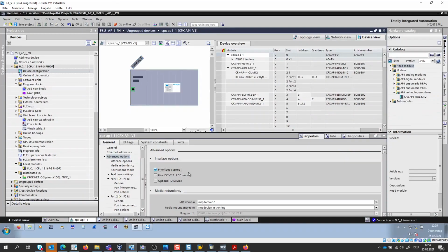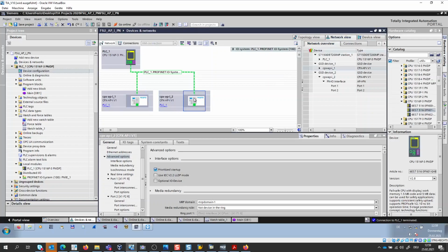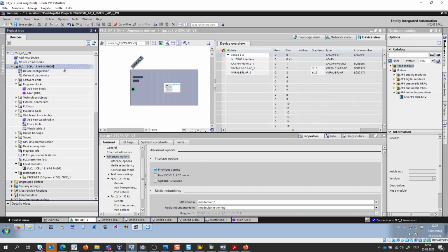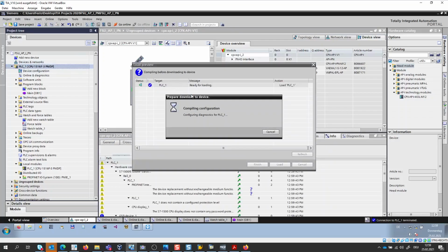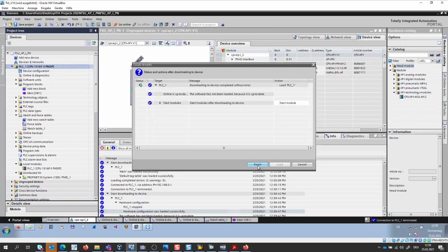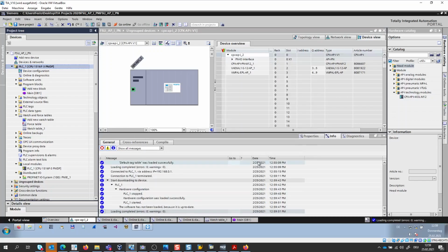If I activate the first API Profinet slave and the second API Profinet slave, then I'm telling the slaves in the first step, hey, come on, after power off and on, be online faster than before.